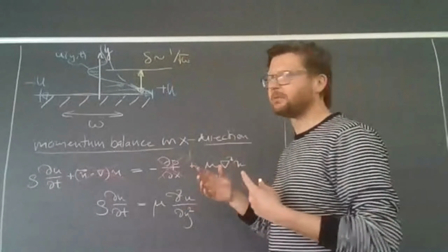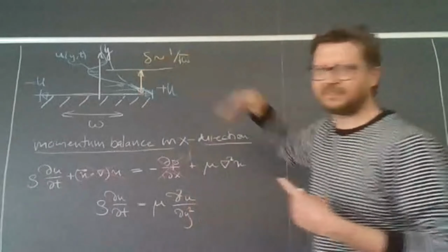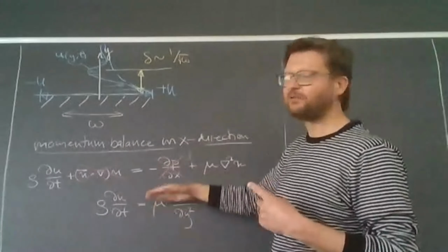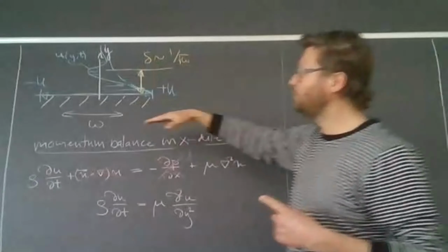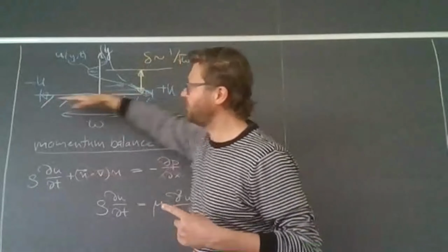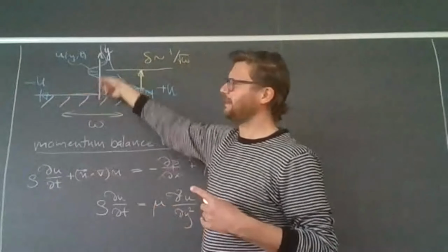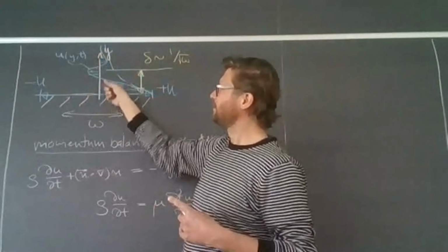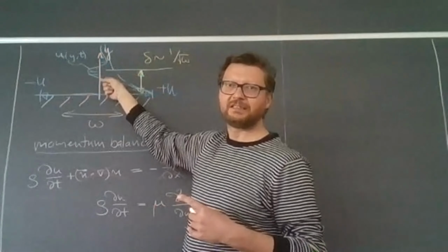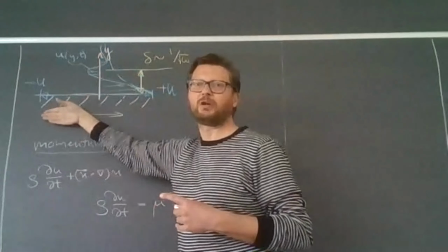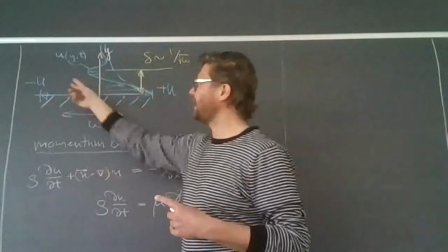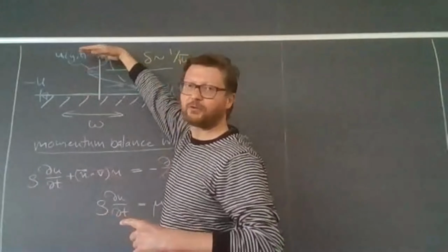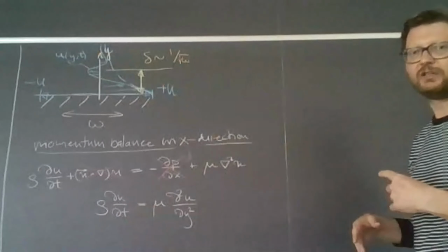And now it should also start to become clear why we have this boundary layer thickness. The viscosity tells us how fast this is moving in. At the same time, if the frequency is too high, the velocity with which the momentum is transported into the fluid is too slow. So by the time the fluid particles notice that something is moving in the wall, the wall is already moving in the opposite direction. That's how this wavy motion is coming about and why it's slowly traveling upward. It looks like a wave traveling into the fluid.